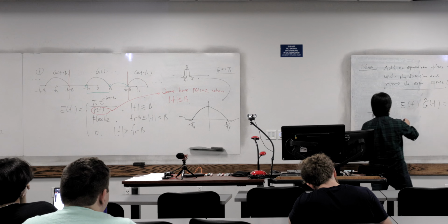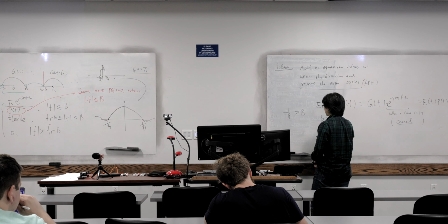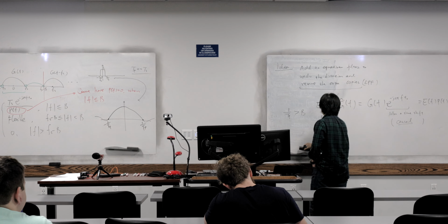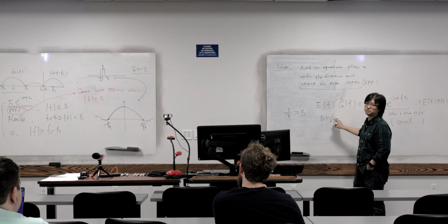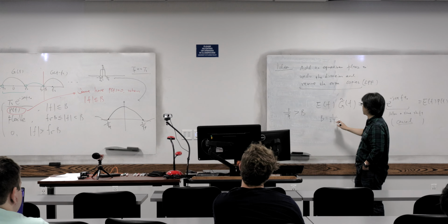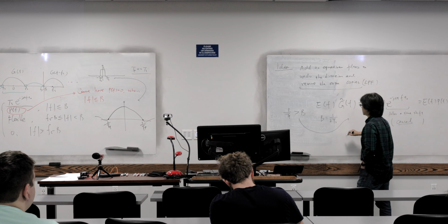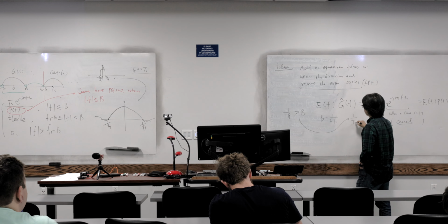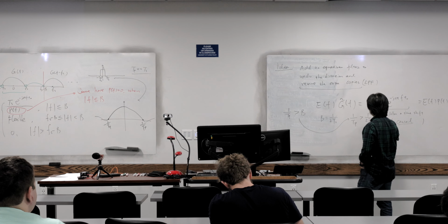So basically B equals 1 over 2 TS. Let's assume this is B, okay? So if we replace that here and see whether that makes sense, 1 over TP bigger than 1 over 2 TS. So this basically means, we reverse it, TP less than 2 TS.